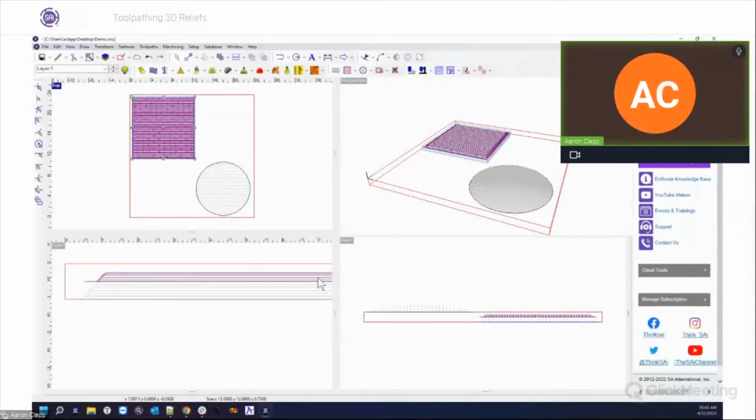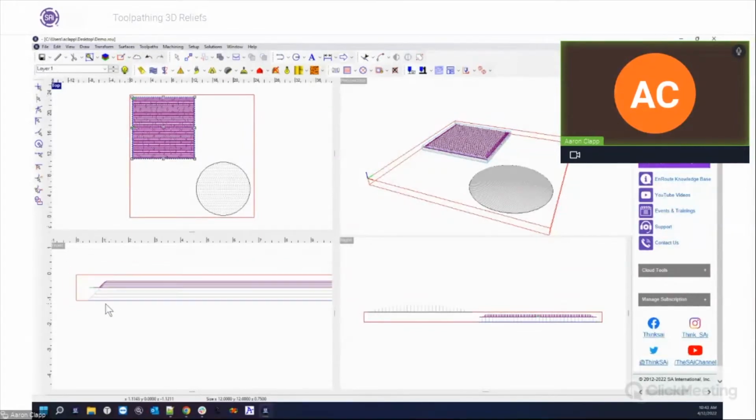So what we want to do here is we need to calculate, okay, what is the thickness of our relief, and then how deep is that relief in relationship to the rest of our material. So in this particular case, if I was doing it like this and cutting the top and everything, I had set at the bottom of my material, I actually need to set this to 1 inch.